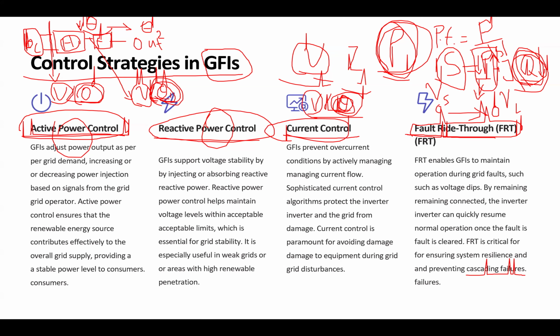It's basically a rush of reactive power demand from the motor. That rush of starting current is basically a demand of reactive power by motors to create the environment so the motor could get the active power and work. That is what's happening.